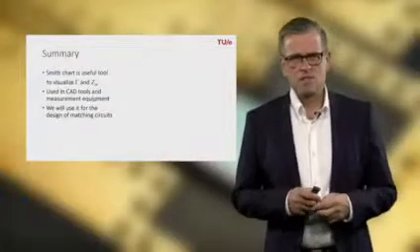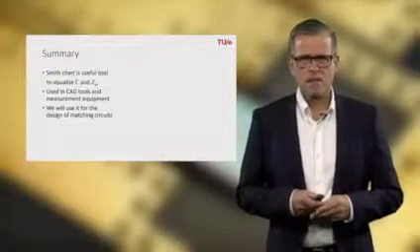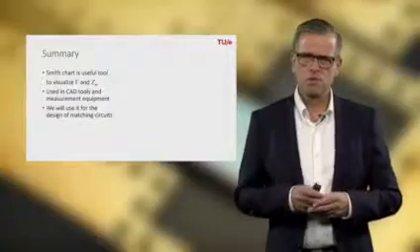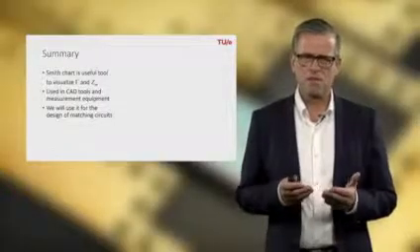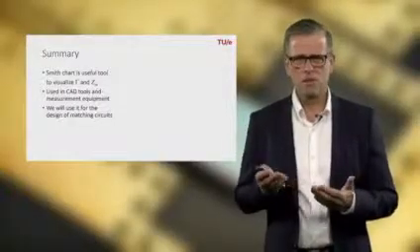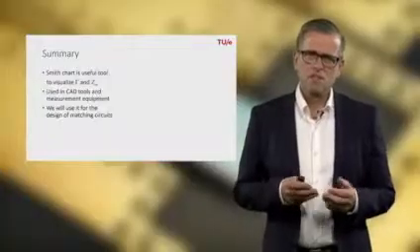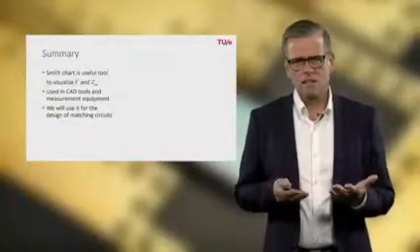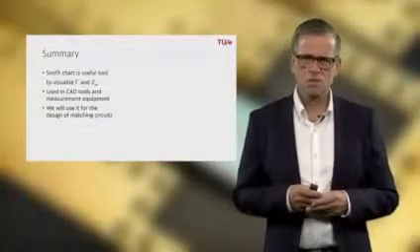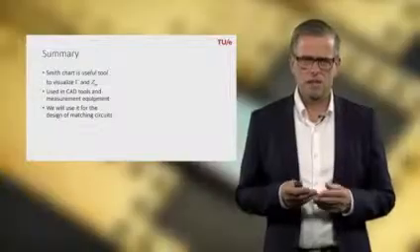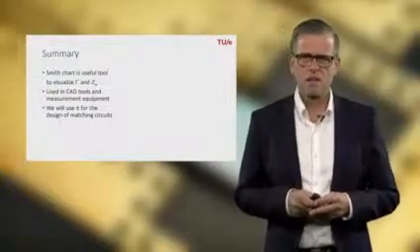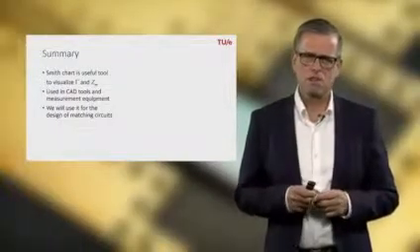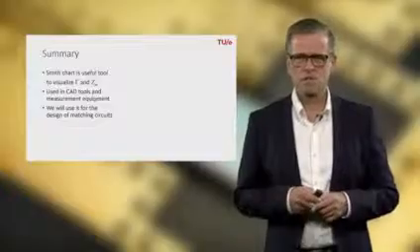To summarize this web lecture, the Smith chart is a very useful tool to visualize the reflection coefficient and the input impedance or input admittance. It is used nowadays in many CAD tools, design tools, and measurement equipment like vector network analyzers. And we're going to use the Smith chart for the design of matching circuits.